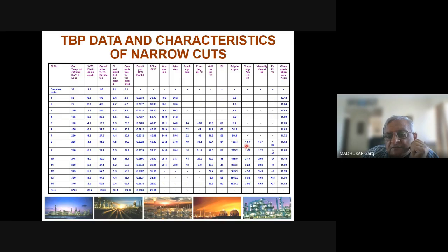Similar is the viscosity, both at 40 and 50. So in our industry, we end up doing viscosity at least at two temperatures to determine how the viscosity changes with temperature, and then the UOPK. So this is what we call a detailed crude assay, and not everything is reported here. When you do a GC, you get a very large amount of data, so that is all reported.